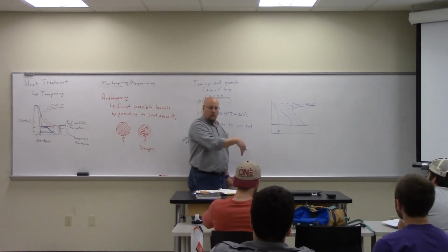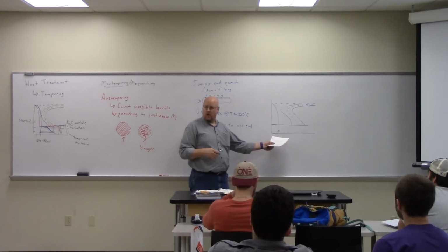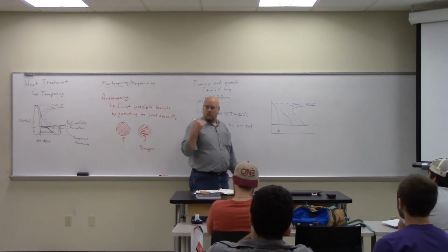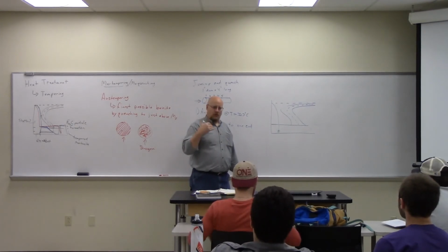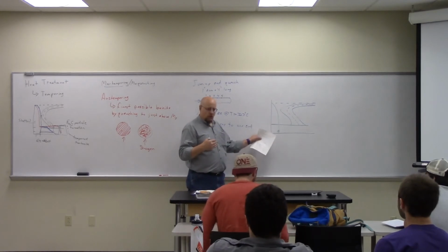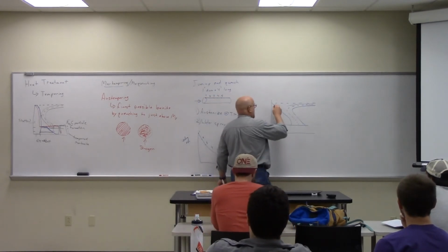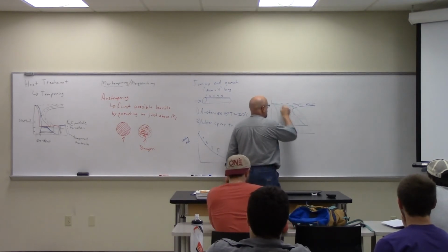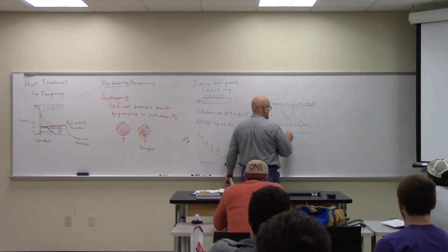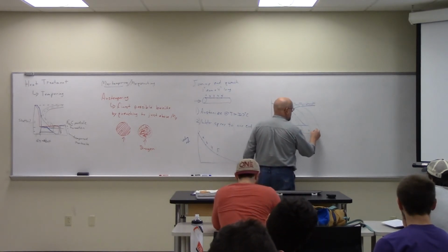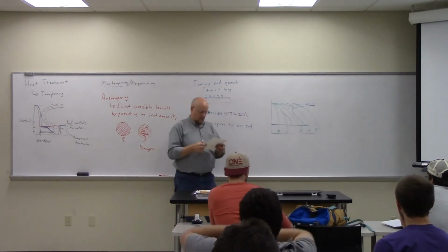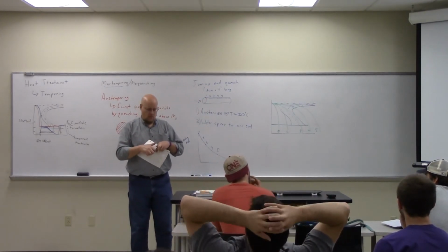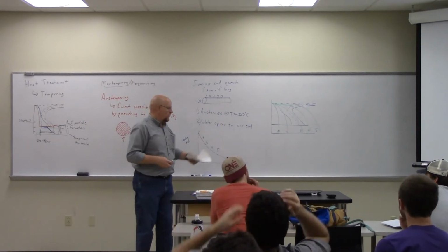You notice I draw it in a curve format because this is log time on the horizontal axis. The cooling rate is linear, the temperature is a function of time at a linear rate, but it shows up as a curve here. So 1 might look like that, then 2, 3, 4, 5. Does that make sense? I get different cooling rates, therefore I go through the different curves at different points.